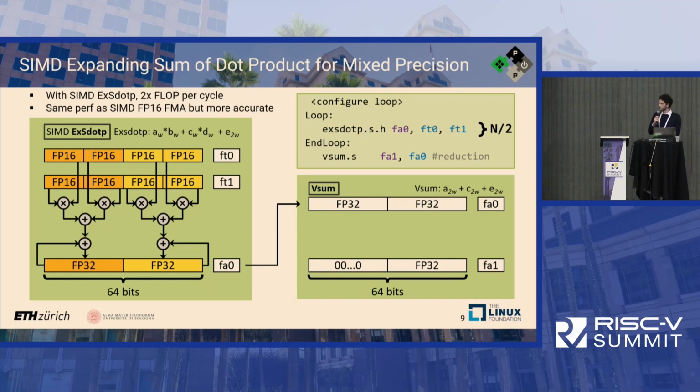Finally, we can find ourselves in the situation in which we need to reduce the results that we have packed in the registers with the accumulator, and we introduced a 3-term addition instruction to be able to do that rapidly. As we will show later, this has been mapped on exactly the same hardware, so it basically came at no hardware overhead.